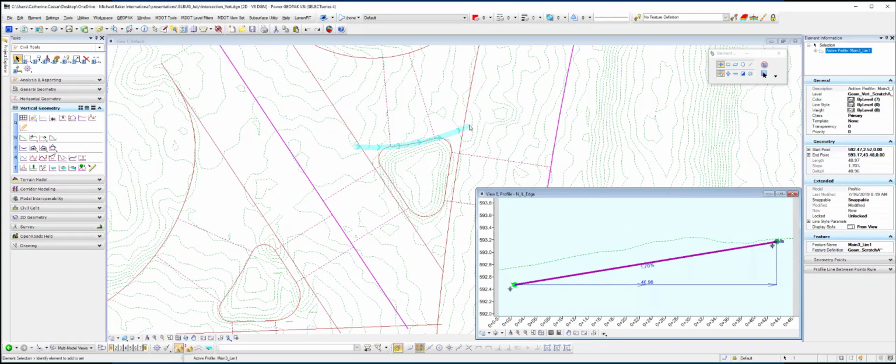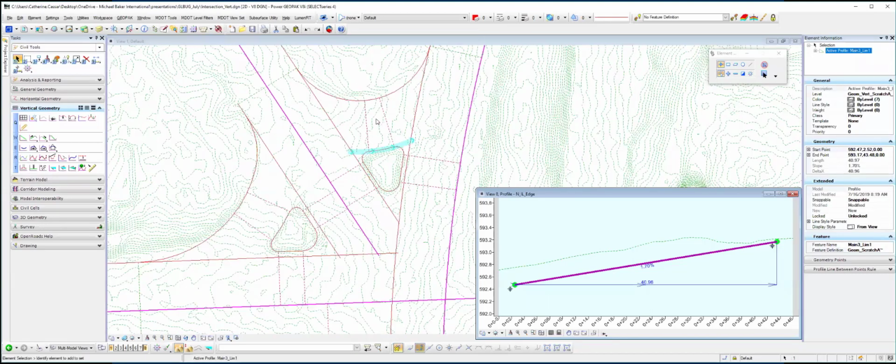You're going to end up with quite a jump between that pavement as the vehicle comes across. So it depends on, again, what you're trying to achieve here. It might not be the best scenario if you don't want your vehicle to have a bump from a 2% that's going this way to a 1.7 that's going that way. That's a 3.7% break, which would be quite jarring for a vehicle. So those are some parameters you've got to be mindful of.